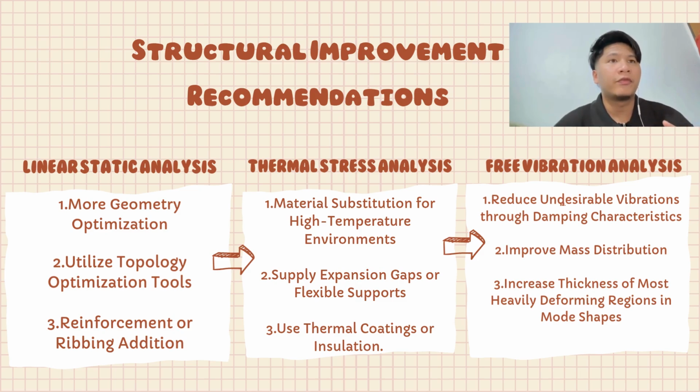And lastly, for free vibration analysis, we need to reduce undesirable vibration through damping characteristic. Secondly, we need to improve mass distribution. And lastly, we need to increase thickness of most heavily deforming region in mode shape.